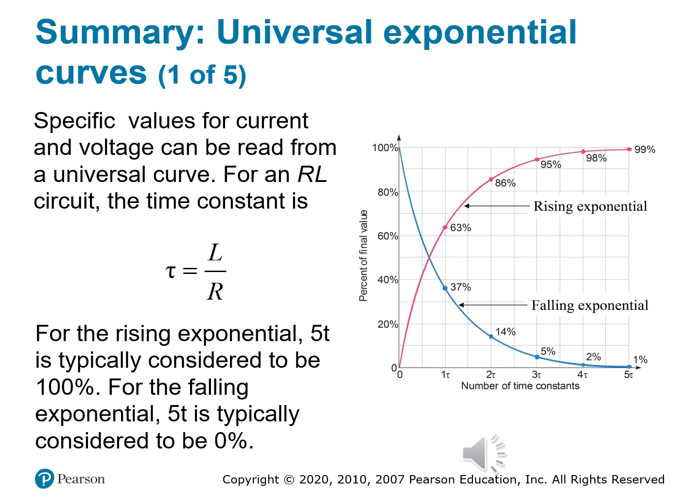Current building up in an inductor after you close a switch, you can track progress. So for 1 tau, the very first tau increment, current reaches 63%. By the time you get to 5 of those time increments, or 5 tau, the response is considered effectively complete. It's 99.9%, really close to 100%. It's close enough, right? We can keep going and say 99.999 something, but at the fifth time constant, we're there.